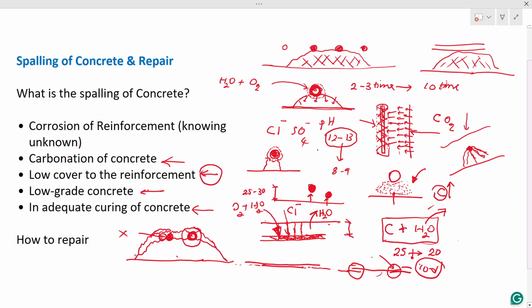Now what you have to do is the concreting. Before doing the concreting, you have to create a proper bond. You have new concrete and old concrete, so you have to make sure this bond is proper. What we can do is apply a bonding agent before the concrete is applied, so the new and old concrete bond together. This application shall be done as specified by the supplier, so you can follow the guidelines specified by the supplier.